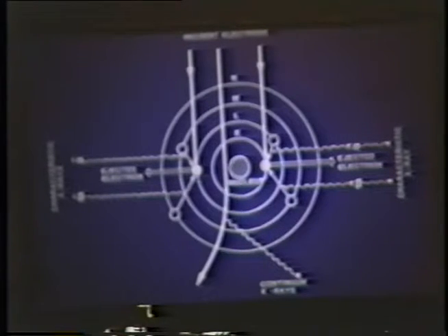The characteristic X-ray fingerprint for each element is the basis of the X-ray analytical technique, as there is a direct relationship between the intensity of characteristic X-rays from an element in the specimen and the number of atoms of that element within the irradiated microvolume. The next slide, please.